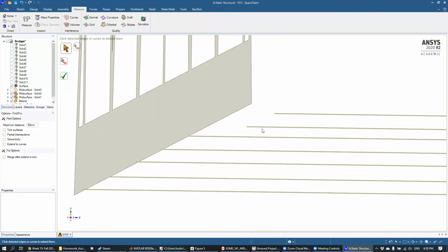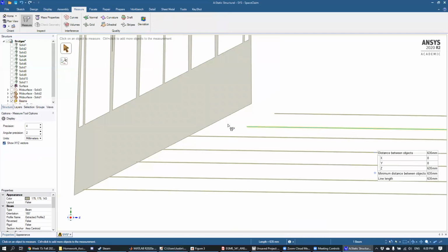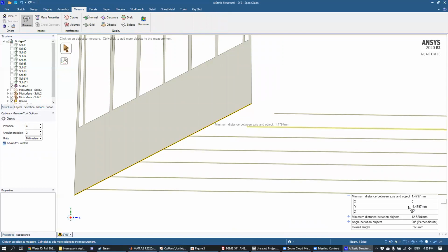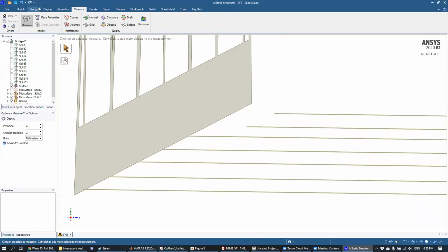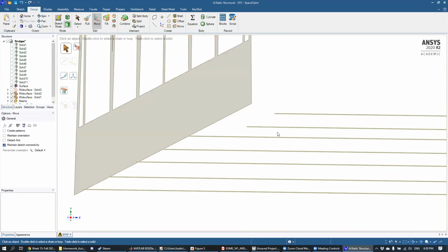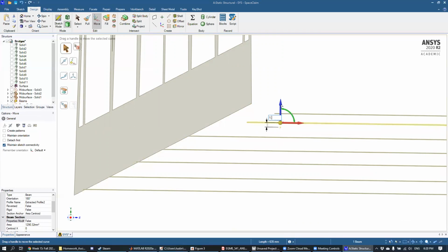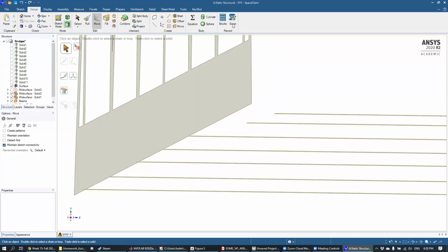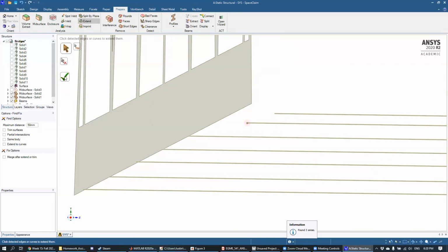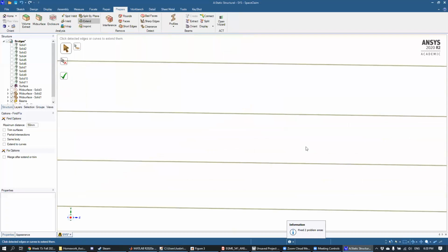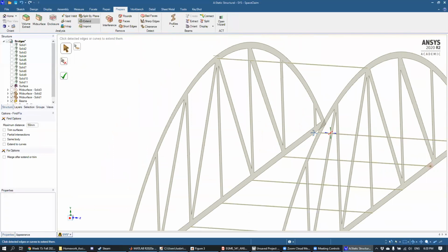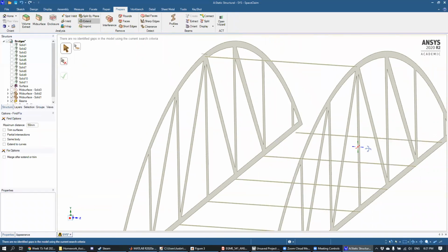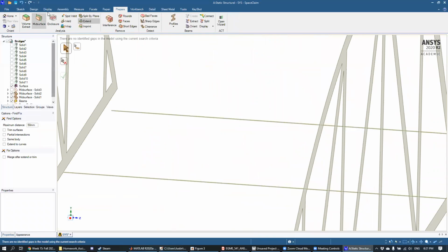Now let's move this guy. Measure first, to find out how much we need to move it up. We can see here that the Y displacement is 1.4797. Okay, so let's move this guy up 1.48. Let's go back to prepare, extend. It shows 3 areas. It's weird, it should only have been 2. Oh well. Okay, and now let's do the last one.